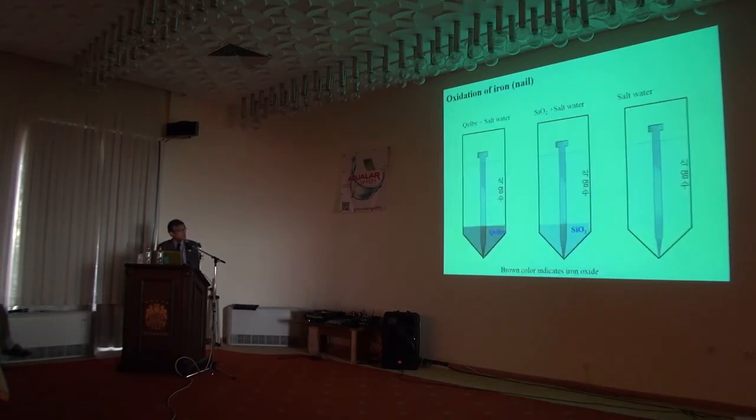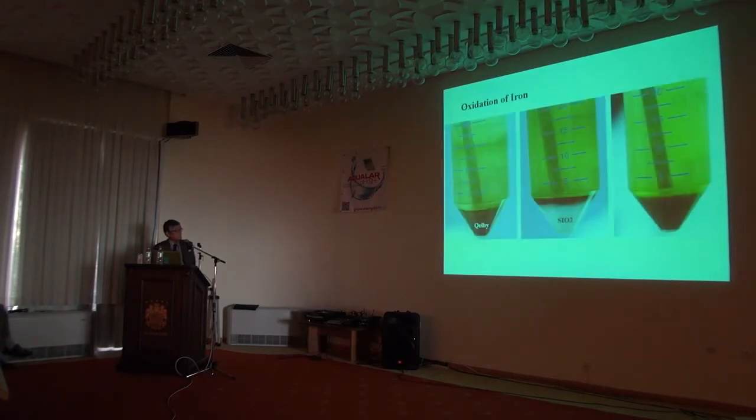In a simple experiment, we put iron nails in salt water mixed with carbon, and in silica with salt water, and we compared the oxidation. After 4 days, the carbon mixed salt water shows the lowest amount of scale. The brown color indicates the iron oxide, as seen in the photograph.